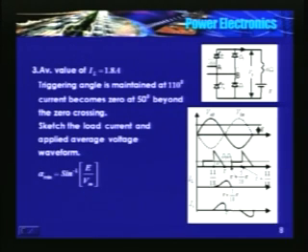That half waving effect is not there here irrespective of alpha, because immediately in the negative half, at omega t equal to pi, D3 starts conducting and this turns off T1. That is not the case if I replace D3 by a thyristor and T4 by a diode. If I interchange these two, then we may have a half waving effect, I told you, because T1 continues to conduct till T3 is triggered. Just to remind you, nothing to do with this problem maybe.